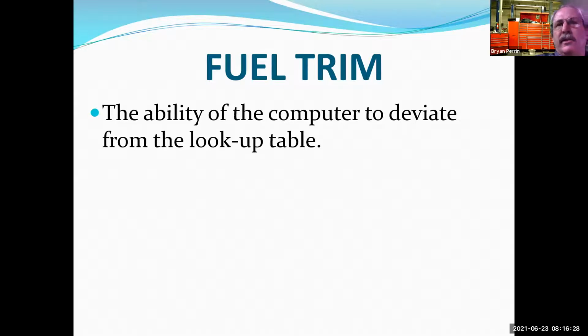And understanding that it's on time. Okay, now let's start looking at things that are going to cause it not to deliver the right amount of fuel in that time, or do I have a bad sensor? Do I have some plugged injectors? And I've run across some really interesting vehicles, and I've written some interesting case studies on those types of issues.